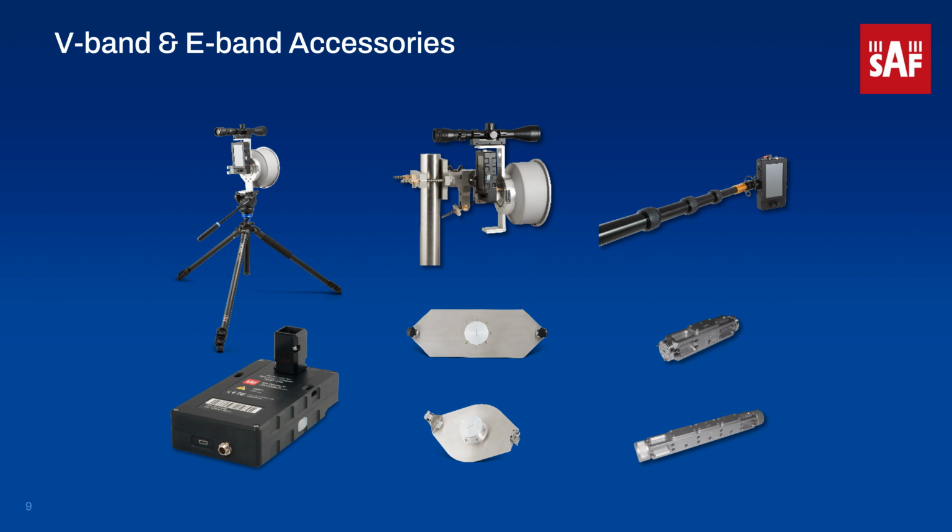When we get to the accessories for the V-band and E-band Spectrum Compacts, which are the Spectrum Compacts from 56 GHz to 87 GHz, there are also dedicated parabolic antennas with tripod, and a horn antenna that can attach directly to the Spectrum Compact. As well, there are waveguide attenuators if the signal you are measuring is too strong for the RF input on the Spectrum Compact. So you can add the attenuator.